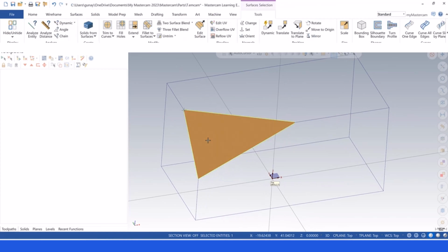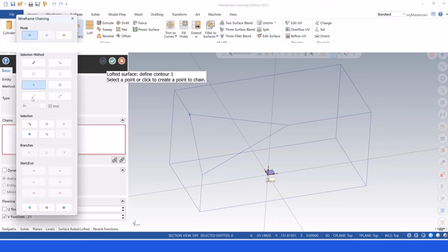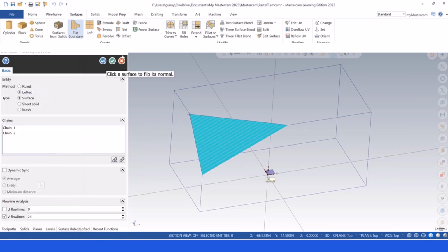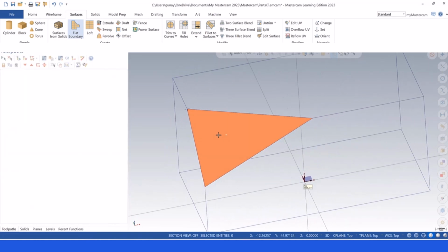And after that, okay, let me select that face and then delete it. And then let me turn back to the loft options. We just need to hit loft and then single options. We need to select this one and this one. And then according to this perspective, we can easily create our face.